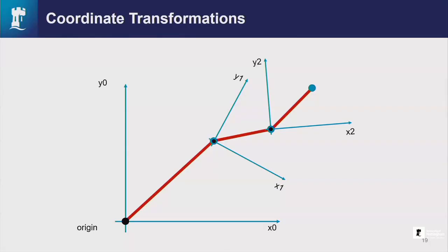Then I'm going to extend that to a matrix formulation that will allow you to work out, given the position of our end effector within its own frame, how we go from its frame to the frame before, and finally come up with a set of coordinates relative to our fixed base coordinate system. Okay? All will make sense.